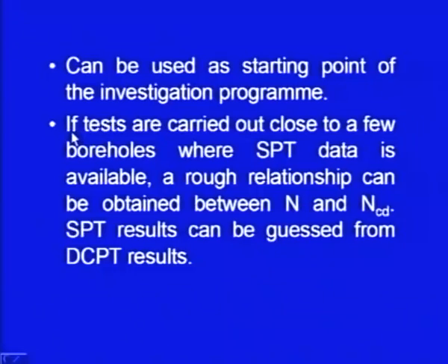Next advantage is, if tests are carried out close to few boreholes where SPT data is available, a rough relationship can be obtained between N and NCD. SPT results can then be guessed. This is what I was discussing. Suppose you have a very big area, then what you can do is you can do some SPTs, and quite close to them you can do some DCPTs.